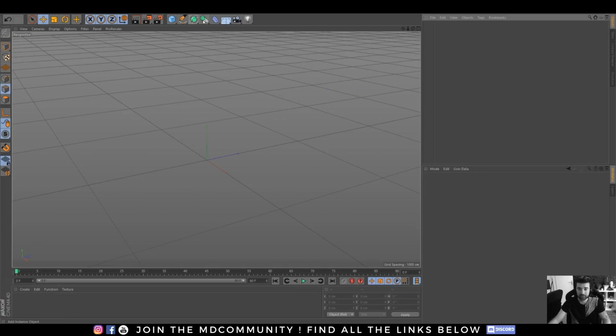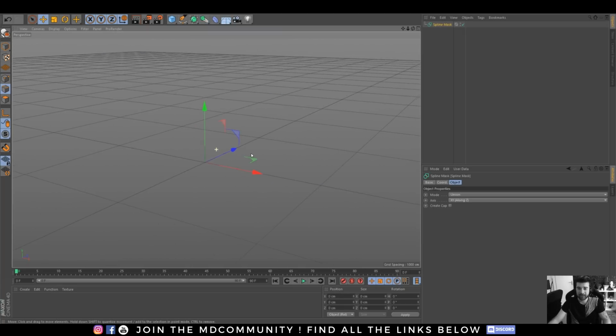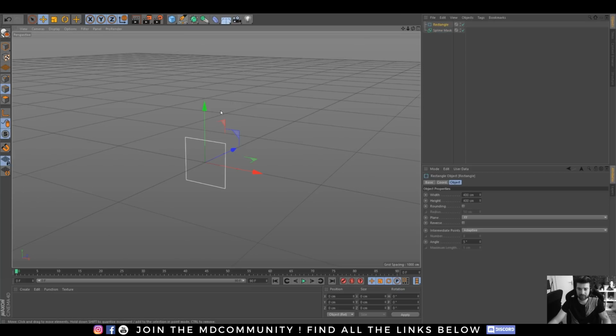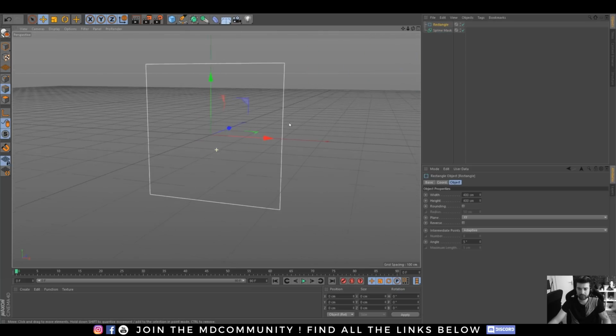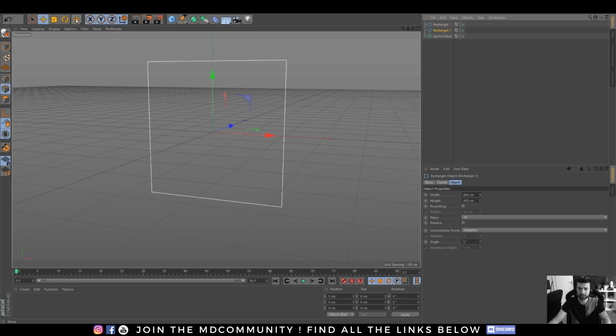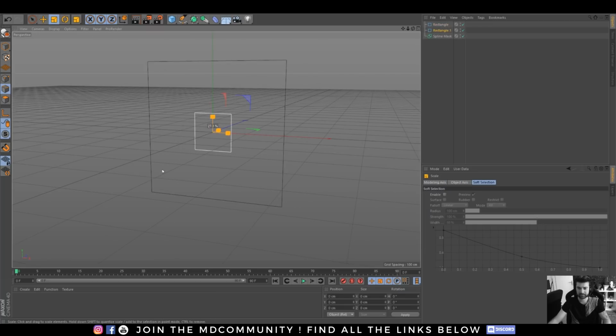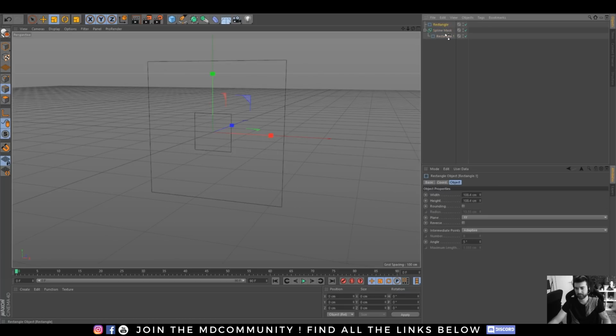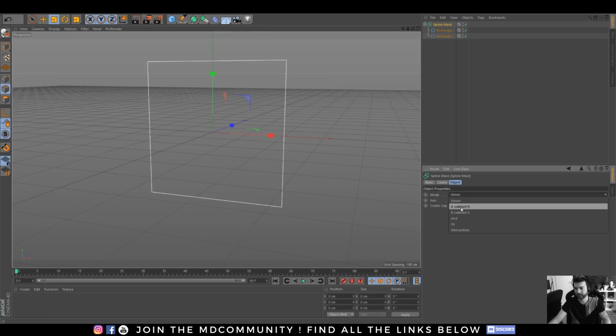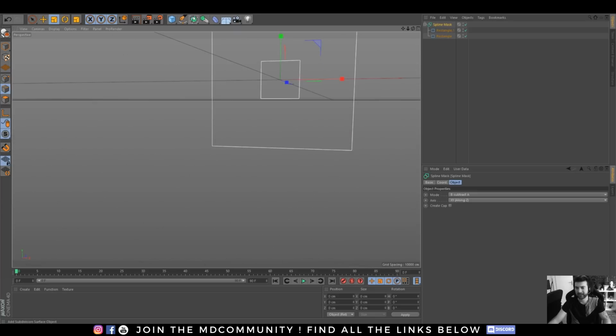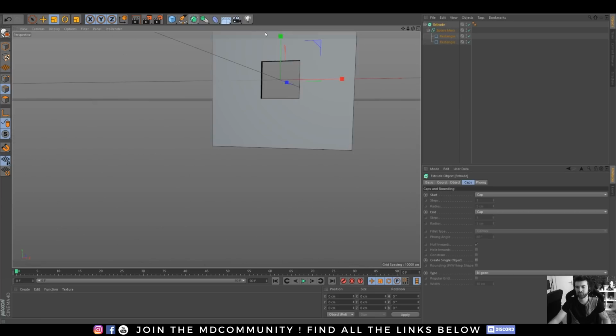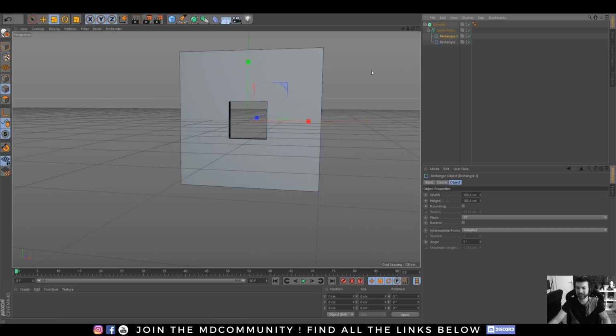You can also use the spline mask and create Boolean operations. Let's take this really nice rectangle. Let's do another rectangle. Let's decrease it. Let's put both inside, and let's create one A subtract B. And let's take, for example, the extrude right now. Okay, it's all connected. That's really, really nice.